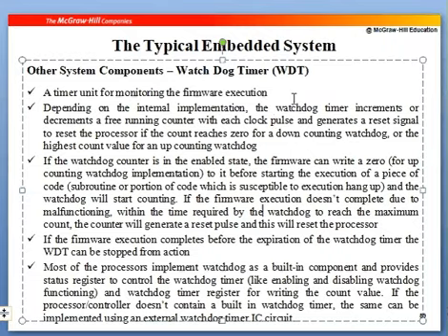So firmware essentially will have the boot program to run the machine and enable your system, that is ESP8266. If you want to start that IC, then firmware is required, that is booting your IC. Along with that, firmware will also include the baud rates which are essential for transferring data from your Wi-Fi to a microcontroller. So all that relevant information is essential. On some occasions firmware will be dumped onto the IC, and in some situations firmware will not be there.